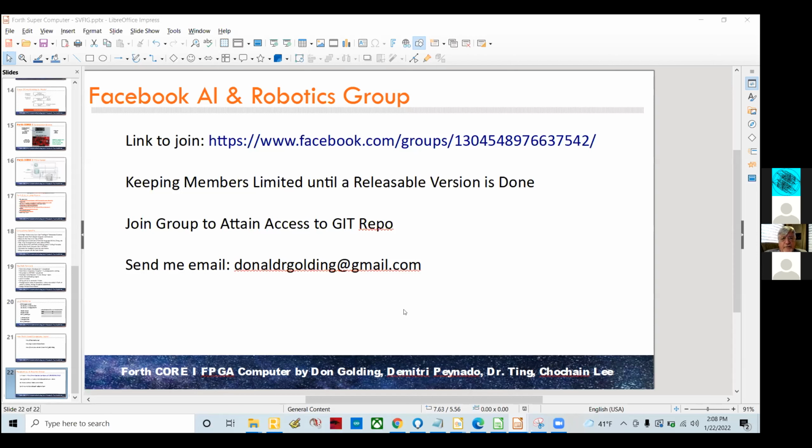Okay, I don't see any more in the chat. Anybody else have a question? Yes, I do. Why did you state such high numbers for RISC-V cores? There are RISC-V cores like the bit serial SERV core, which fits in a few hundred LUTs, and even a parallel core like the PicoRV32 fits in about 800 LUTs, or 2000 with all options enabled, which includes optional instructions.